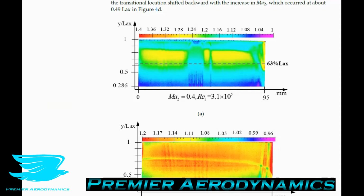So in other words, due to variability in the flow and the coating on the surface, the intensity was not uniform in the regions where it should have been uniform. There were some slight variations. However, these variations were very small compared to the major variations between the turbulent and laminar regions. So even though you do get these small variations, overall you can actually see the difference quite clearly between the laminar and turbulent boundary layer sections. So that makes it very easy to find where this transition point occurs.